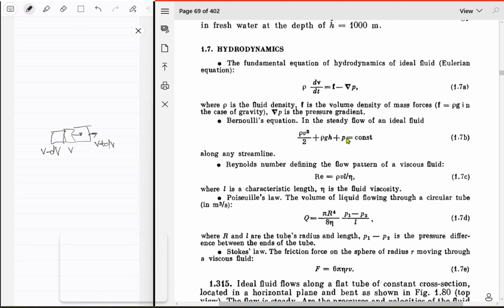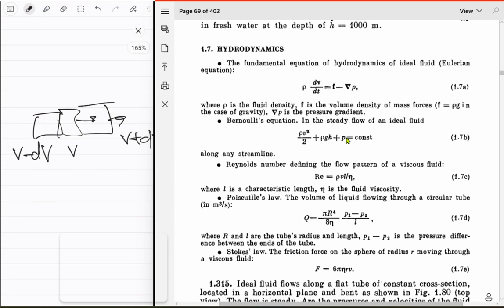But now I know that viscosity is not the way it's taught in schools. Instead, it's a combination of momentum diffusion and also the actual intermolecular forces, right? So the reason for viscosity, at least in ideal gas, would be that these blocks share molecules constantly, right? So they have a habit of exchanging these molecules, and molecules from this block have higher velocity, and over here they have lower velocity.